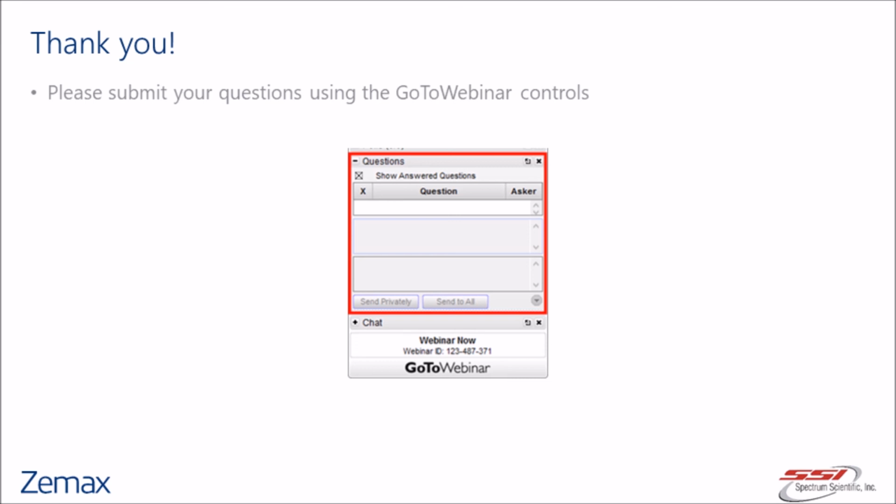So it can be replicated, but measuring it is difficult. Yeah, and you can make an optical model of your test setup to see if the slope is so high that the fringes in your interferometric test can't be resolved, and that's often what limits your max slope on these parts. And that's what you demonstrated earlier, right? Yeah, briefly, very briefly.